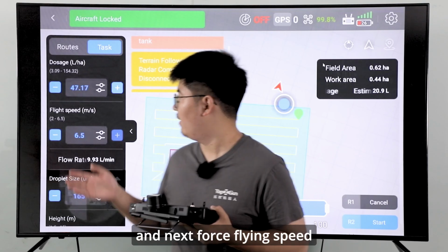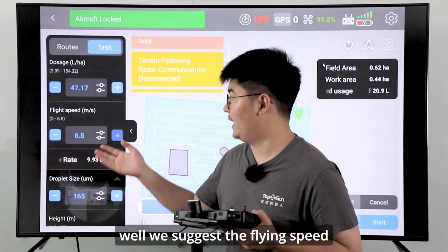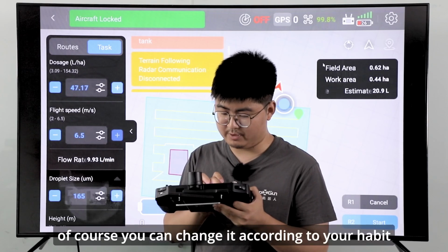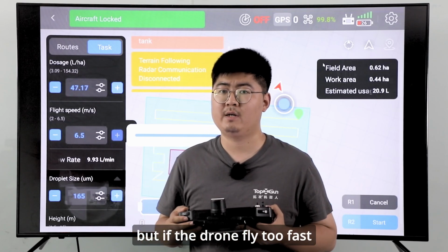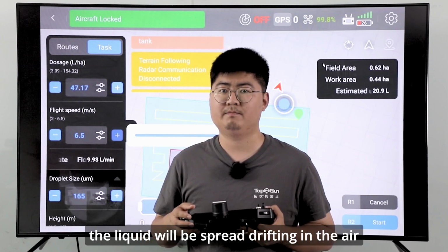And next, for flying speed, well, we suggest the flying speed be controlled between 6 meters to 8 meters per second. Of course, you can change it according to your habit. But if the drone flies too fast, the liquid will be spread, drifting in the air.